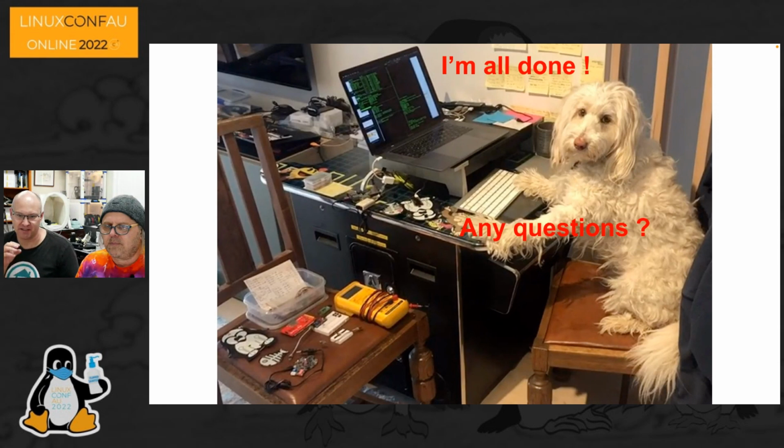So things like the oscillators in the analog front end that read from the antennas to measure your hand position and those sorts of things, there's been some testing done of those, and we can see on the oscilloscope that the signal coming out of them makes sense. Oh, and better than that, we've actually got the FPGA counting the frequency. So there's a couple of diagnostic tools.